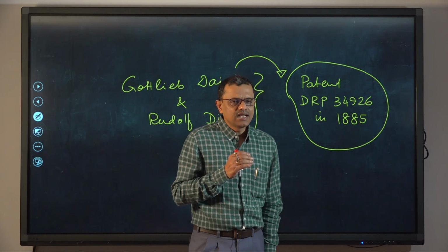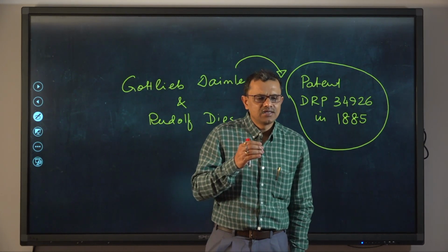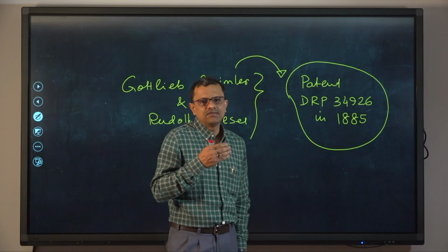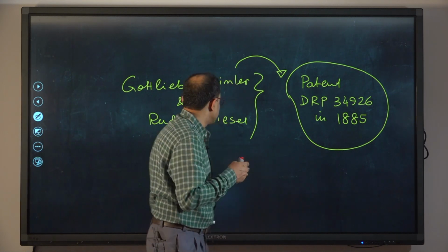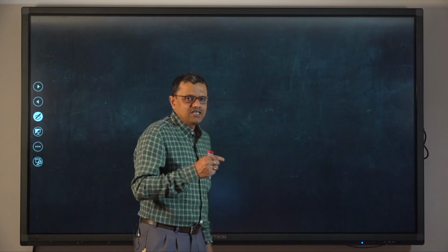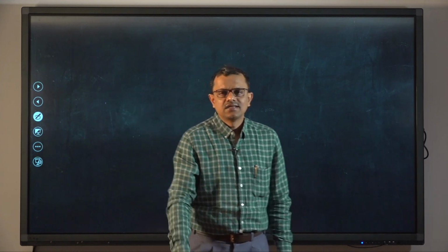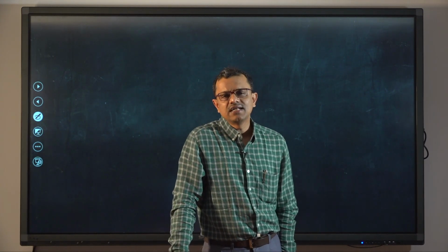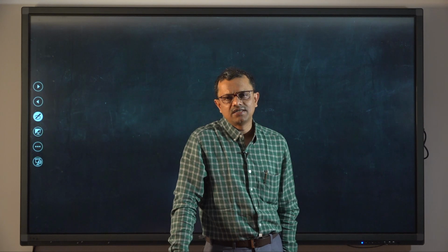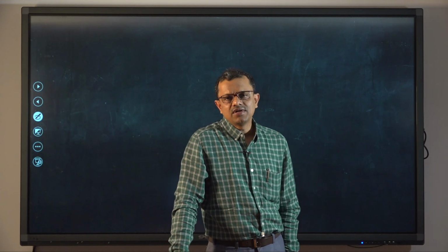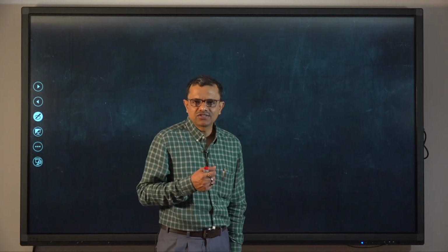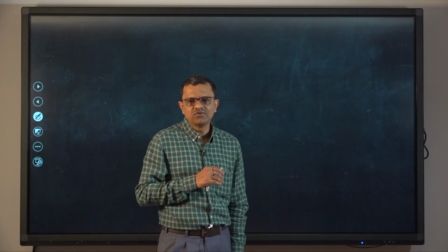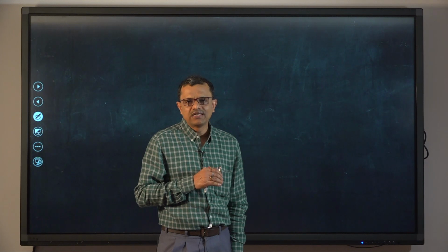Also, if we go to the next slide, we all know that if the engine attains higher altitude, the density of the air will certainly reduce. Then the mass of air that will be entrapped during the intake stroke inside the cylinder volume will be less because of low density.